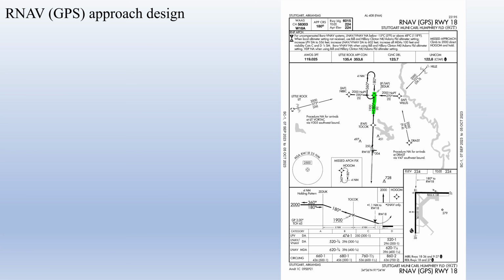They also typically have an intermediate segment preceding the final approach segment. This segment is also usually about 5 miles long and also aligned with the runway. Aircraft approaching the airport anywhere within 90 degrees of the intermediate fix can navigate directly to this fix and then in on the approach without having to perform a procedure turn.